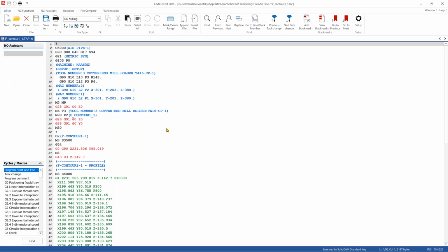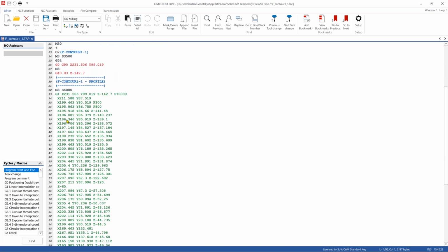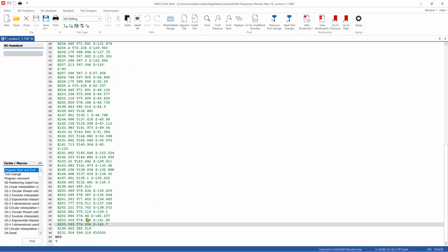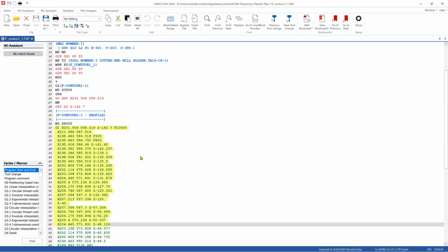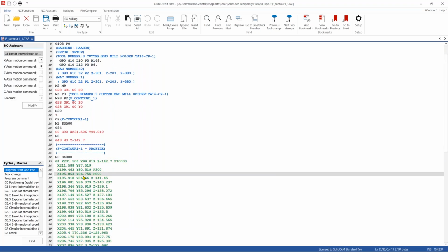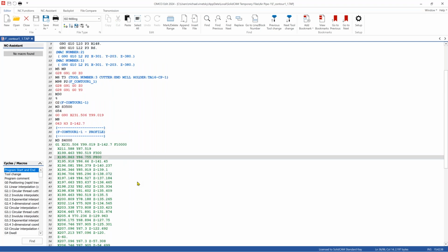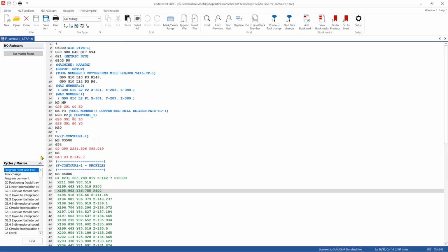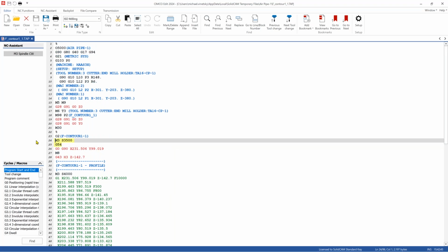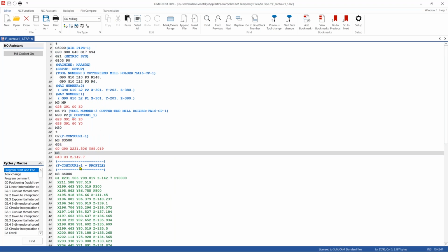And what I see here, you see it immediately. I have a long toolpath. There are no arcs here. Everything is done by lines. Arcs are made by short lines, and long lines by long lines. But there is no compensation, of course, and there is no plane. I mean, no call to G17 or G18 or G19 plane, because it's not possible for it.